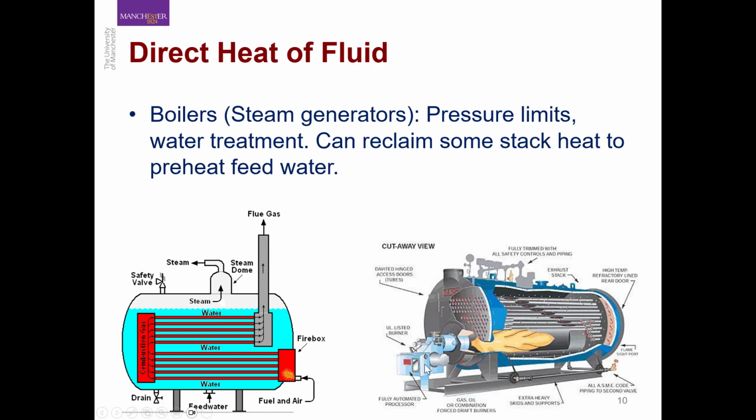And here you have also a viewing window, and these viewing windows are very important because more experienced workers can actually look at the flame, or from the color of the flame they can check if the system has a lot of excess air, or the system is choked. It means that you don't have enough air. So by just looking at the flame they can adjust a perfect air to fuel ratio in these kind of systems. So these kind of fire heaters use the mechanisms of conduction and convection.